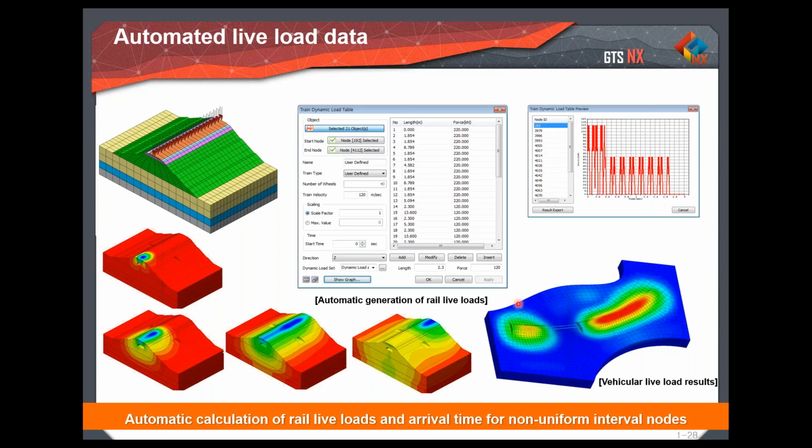So what is the effect of your train dynamic load on the existing embankment, so that we need to go for a concrete lining underneath? It means apart from the ballast or what we use in regular conditions, we need to go for concrete lining, or we need to come to that conclusion, because not even 1 mm of differential settlement is allowed in the case of train rails. So that's why we need to run this train dynamic load analysis rigorously for upcoming high-speed railway line projects.